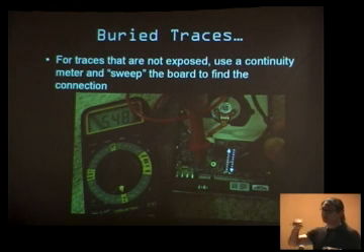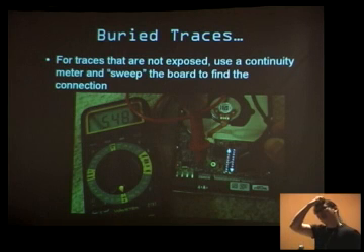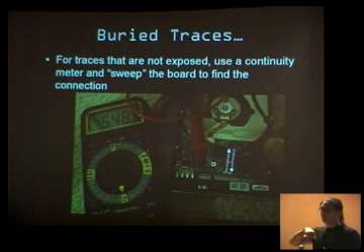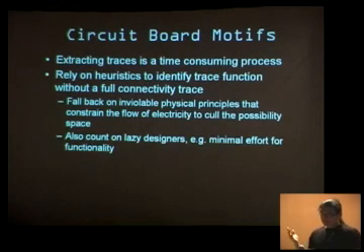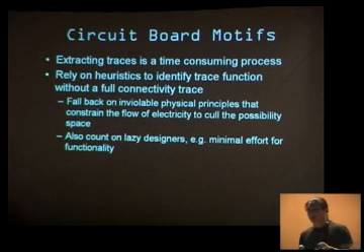It sounds like a lengthy process to trace out, but you can usually find in 10 seconds or so where the connection is going. You have a general idea where it's going, you're just running across all the pins of the chip and so forth. Eventually, you just hear the beep, and you kind of binary search and you say, okay, it's pin 42 of U506, and you say, okay, noted, right? So that's one method for finding buried traces. There are more drastic measures like the X-ray machine if you really can't find it.